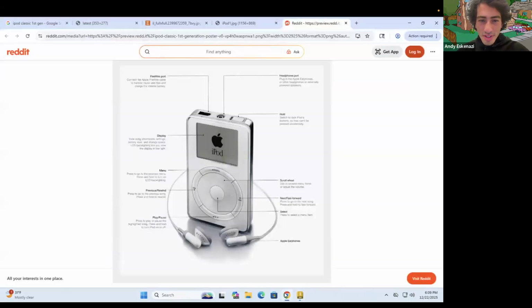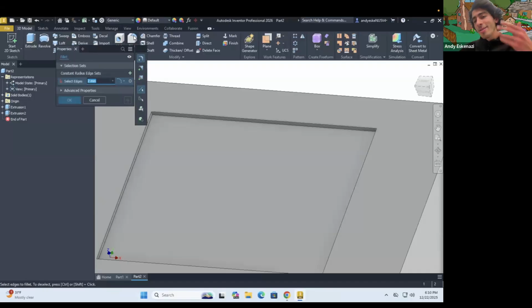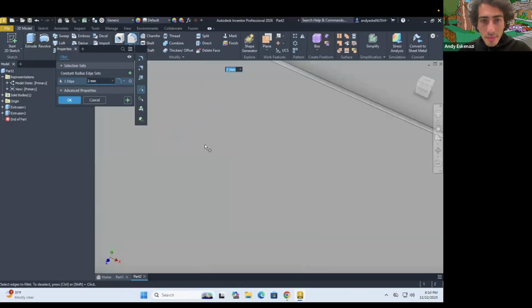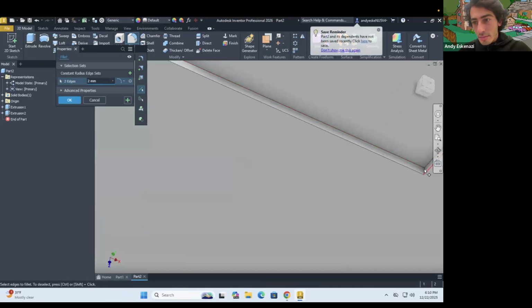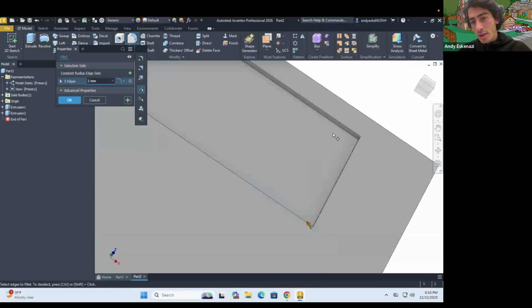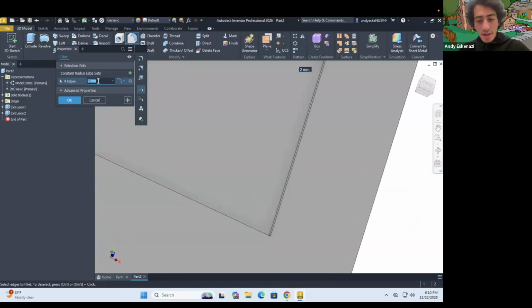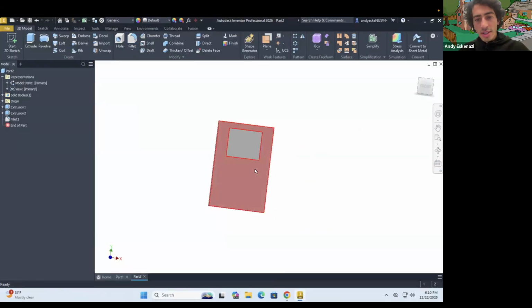Then if you go here, you see there's like slightly very small fillets. So I can go here to 3D model, fillet. And again, you could have done the fillets on the actual sketch because there was a fillet constraint. But I'm just gonna click right there. Click right here. Click right here. Right here. And we're gonna say we want these to be 5. Good. Well, so that doesn't look too bad.